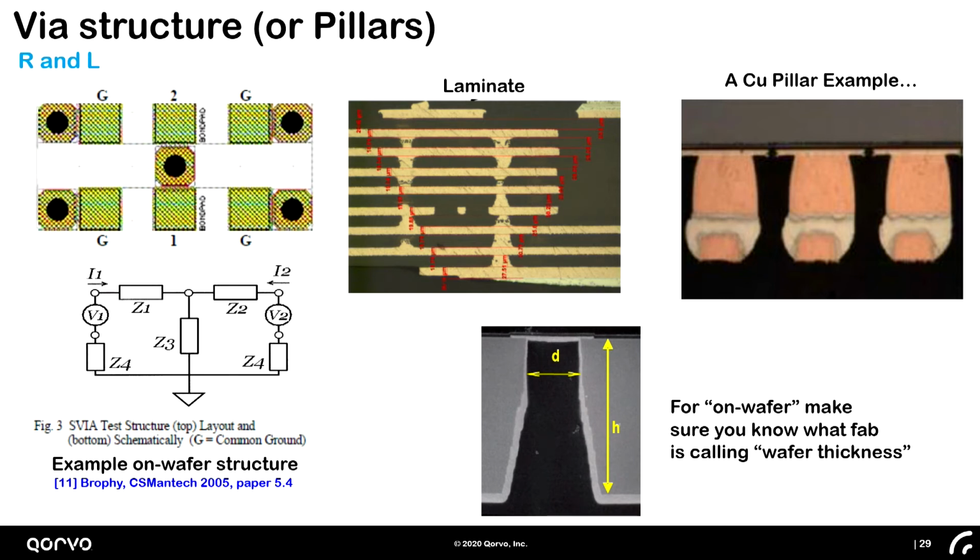And this just gives you an idea of some of the problems with laminates. You can see these vias are not cylinders at all, and it's not on some of the layers. That's kind of a problem. Copper pillars, which are quite often used for assembly, you can go through, there's no two pillars that look alike, right? But people always simulate these just saying it's a cylinder, but when you go to match it to the board, solder goes all over the place, right? So that, I would assume, simulates differently than if it doesn't go all over the place.